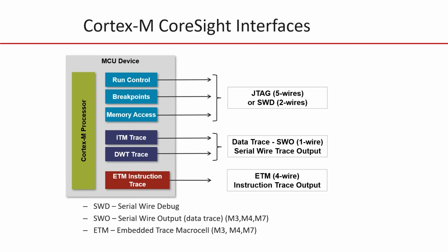So in order to get the serial wire out, we may have to do some further configuration to the processor. This is in the form of a small script file, which will convert this pin to be the serial wire out pin from its standard setting of a GPIO pin. But this is a bit dependent on the silicon vendor, so it will vary from device to device.